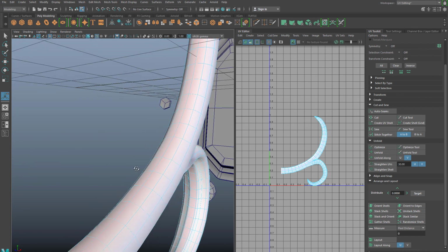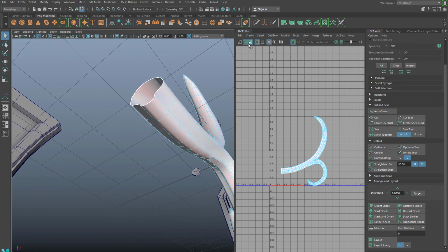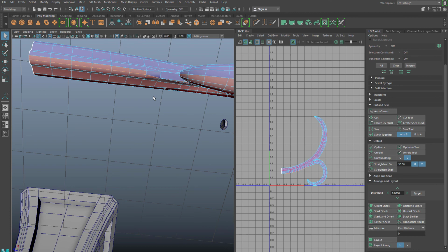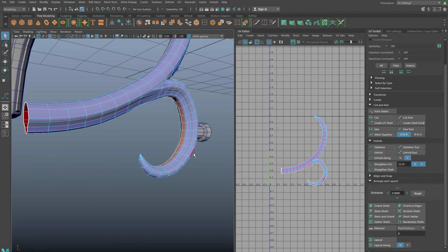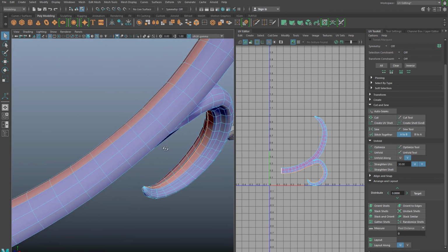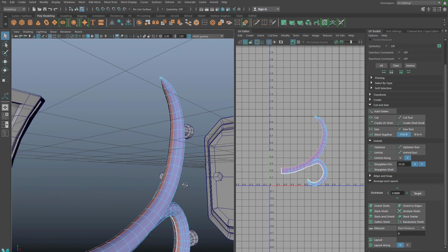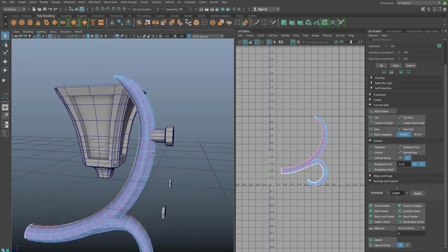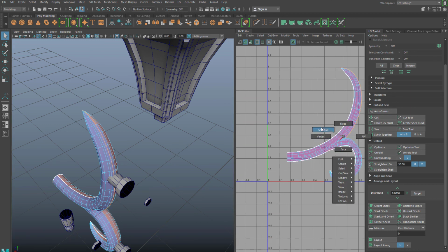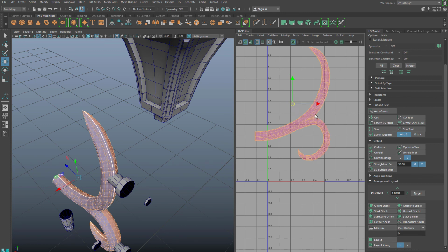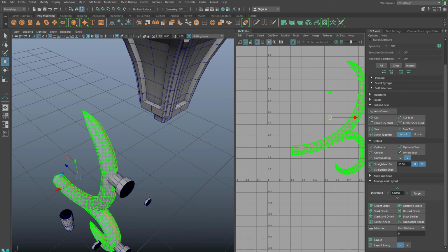So what I want to do with this one, honestly, is let's turn the distortion off. Cut that, or basically right down the middle. And then same thing right up on this side. Go ahead and cut that. And then along the back, cut that. Now let's see if, nope, still all one shell. So let's cheat and hit unfold.